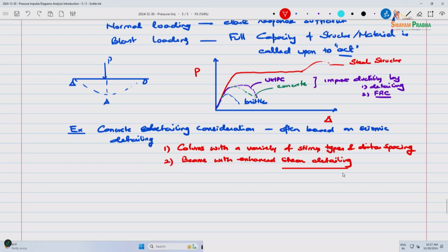To get the response that you need, for example, even at high level of protections, if you want to get a response of 8 degrees, you really need to focus on good detailing at the shear ends, wherever shear is high, ensuring integrity out there and then making it more ductile in the process. So, we borrow these concepts